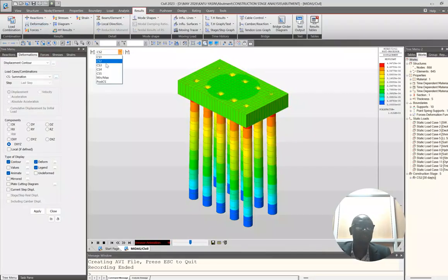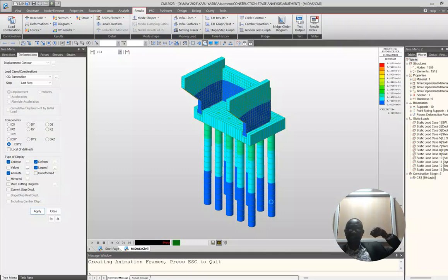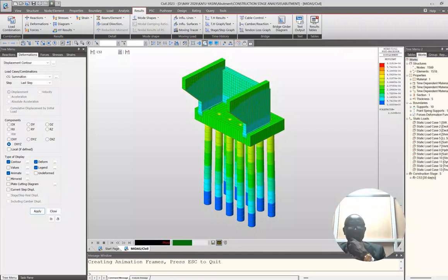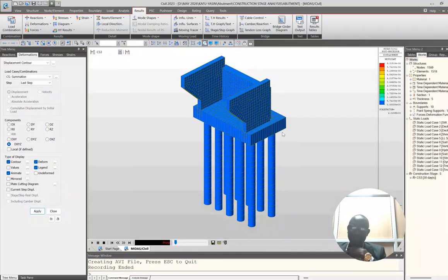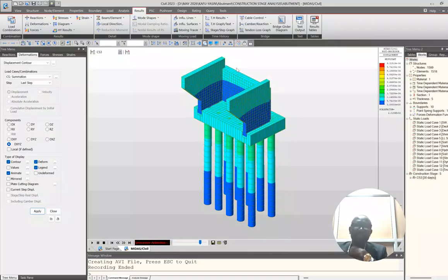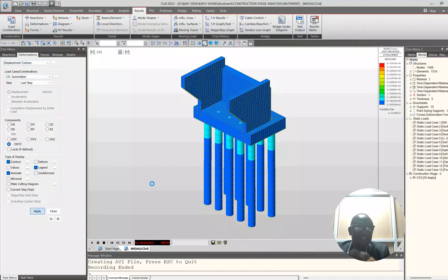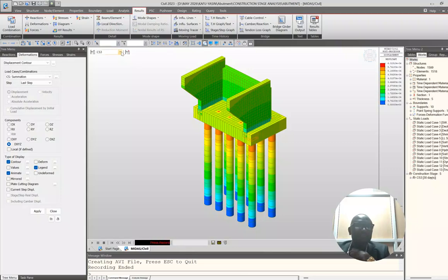And then if you put your third level, the abutment is in place. Then you apply that. We are not into the amount of force we are applying; we're just trying to appreciate that. Actually, it is very important that you take note. You see now, once you add on the third stage, which is the abutment, before you have added your ballast wall, you can see the implication. The deformation is already increasing here, almost by 0 point something. So we need to take note, appreciate it and try to do some of these things in a better way.